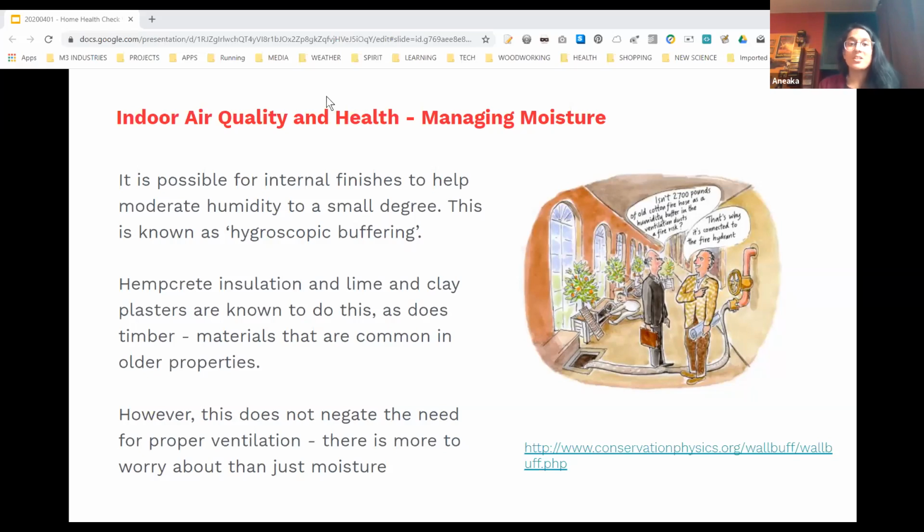This is indoor air. I apologize for the phrasing of the question. I meant to say indoor air is often very dry. There is actually a lot of moisture in the air at that time of year outside, but as you heat up that air, you have a lower relative humidity indoors.